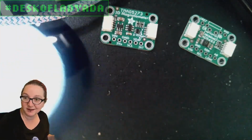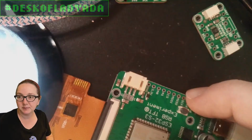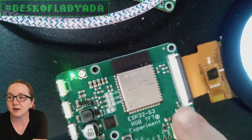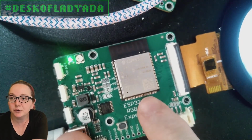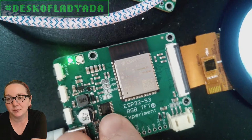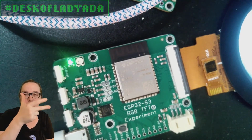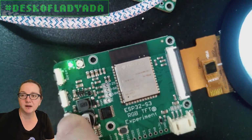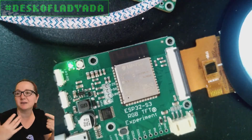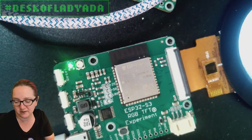Next thing, while this is all happening, we're making a lot of progress adding CircuitPython support for the ESP32-S3 in TFT mode for the RGB TFT. This is the Rev B. You can see that I no longer have any cut traces. And because I'm no longer using these 3 pins, since it turns out you can't use those pins if the PSRAM is in octal mode, I have a GPIO expander instead. Over I2C, this has the TFT reset, chip select, clock, data. These 2 buttons, up and down, are also on that, and then the backlight control, on and off. And some other pin, I can't remember, but basically all the IO is used on this.